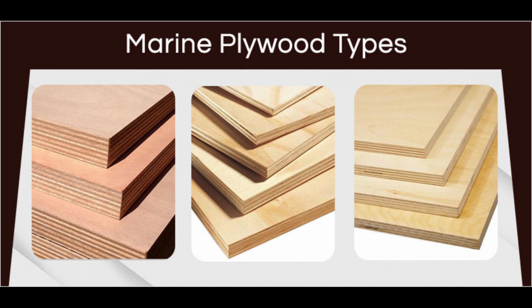This marine plywood can be graded as being compliant with BS 1088, which is a British standard for marine plywood, and IS 710 is the Bureau of Indian Standards, BIS, standard for marine grade plywood. There are few international standards for grading marine plywood and most of the standards are voluntary.